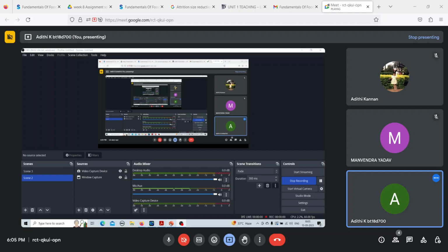And when you substitute m is equal to 1 and integrate from xf to xp, you get energy consumed is equal to kk, which is the Kick's law constant, into natural logarithm of xf by xp, where xf and xp are the sizes of the feed and the product particles, kk is the Kick's constant, and E is the energy required. So this is the formula for Kick's law.